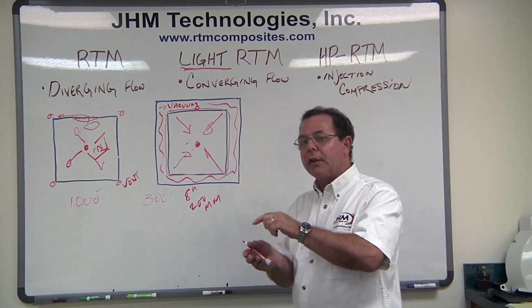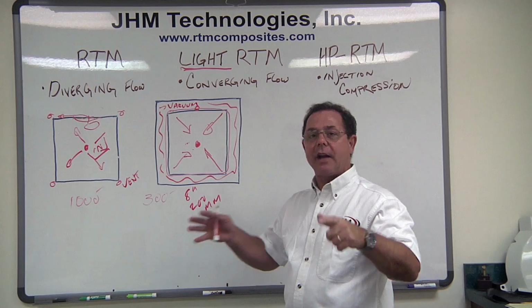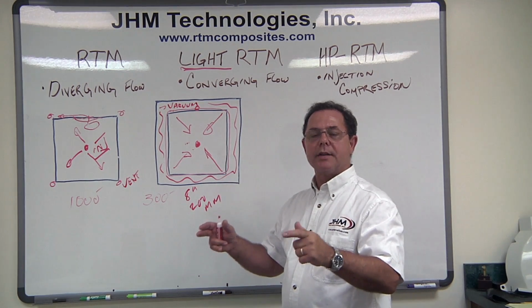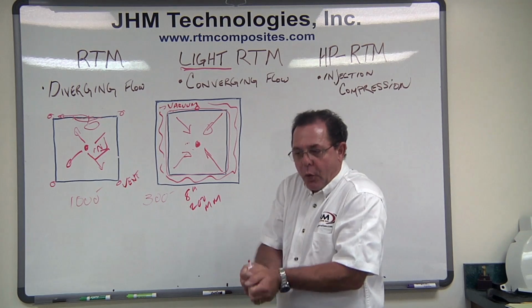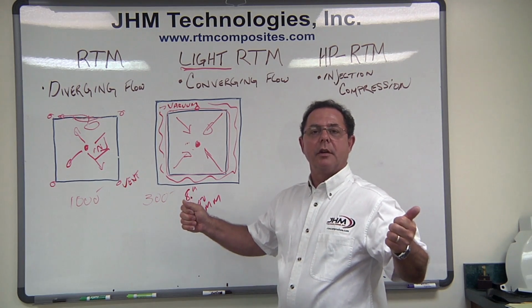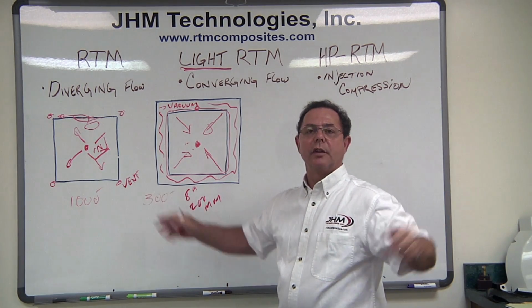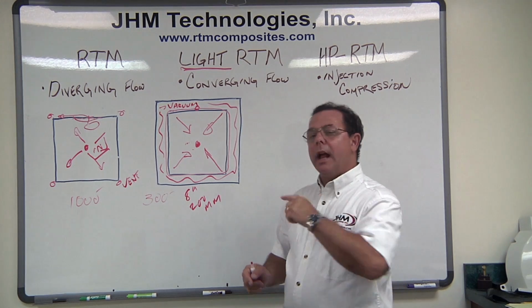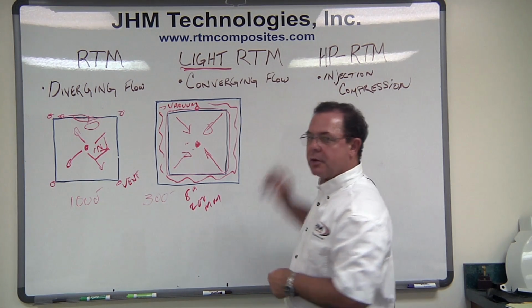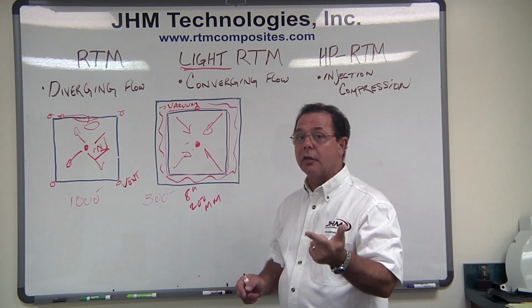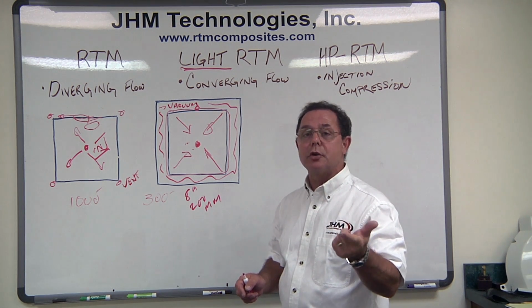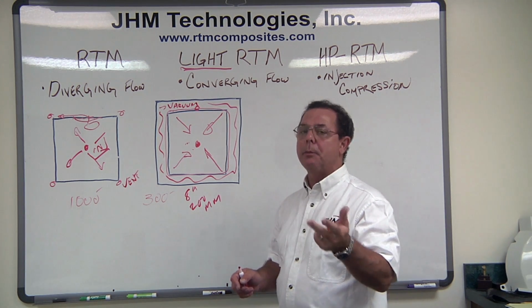By having the mold slightly open, we can inject the resin in faster, put that shot of resin into that mold quickly, and then use the force of a press to form it and force the compression closing, as it were, forcing the resin to the edges. So the end of the story is, with high pressure RTM we can get speed, but we've got to have a press, and we've got to have solid tooling. We've got to have rigid tool sets. Aluminum at minimum, typically it's steel.